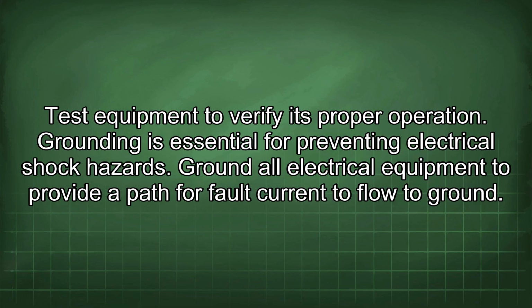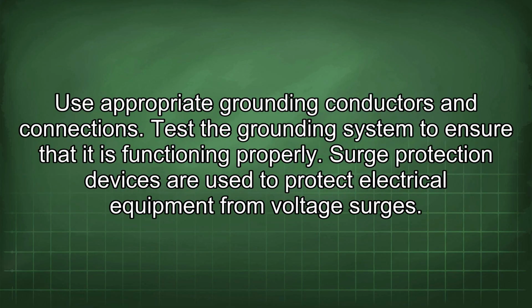Grounding is essential for preventing electrical shock hazards. Ground all electrical equipment to provide a path for fault current to flow to ground. Use appropriate grounding conductors and connections. Test the grounding system to ensure that it is functioning properly.